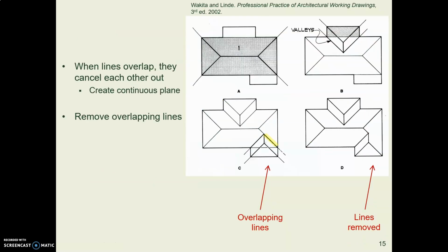And now the secret to tricky overlapping roofs is after you get all these 45-degree lines laid in, anytime you see one 45-degree line lying over the top of another 45-degree line, like we see happening in C here, and what we've got here is some kind of hip-roofed stick-on to another hip-roofed main roof.